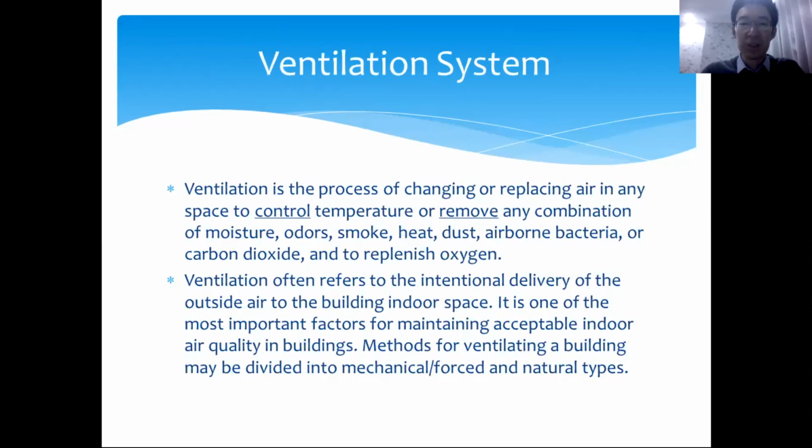So ventilation is the process of changing or replacing air in any space to control temperature and remove any combination of moisture, odors, smoke, heat, dust, airborne bacteria, or carbon dioxide, and to replenish oxygen. This became very important, especially during the corona crisis and the pandemic.